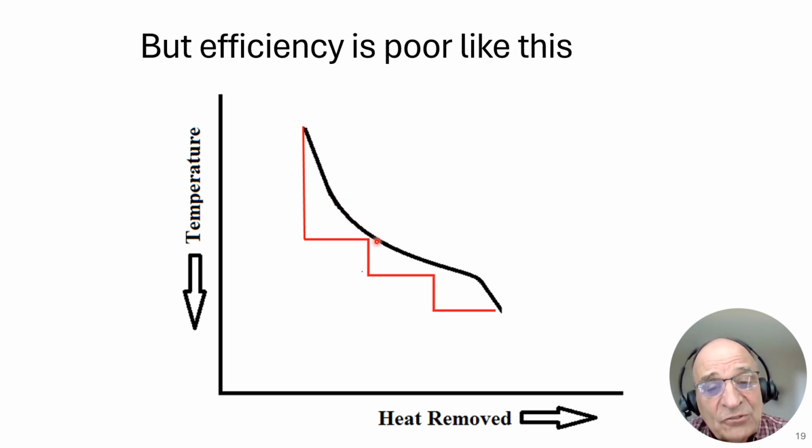And ethane will be dropping out all along here. And as you get to here, your methane's dropping out along here. And then you get to a point where you're 100% liquid, and then you subcool that liquid. That's the LNG liquid. Then this subcooled LNG goes through a JT valve, and you make LNG. You keep the LNG, and you send out the flash gas.